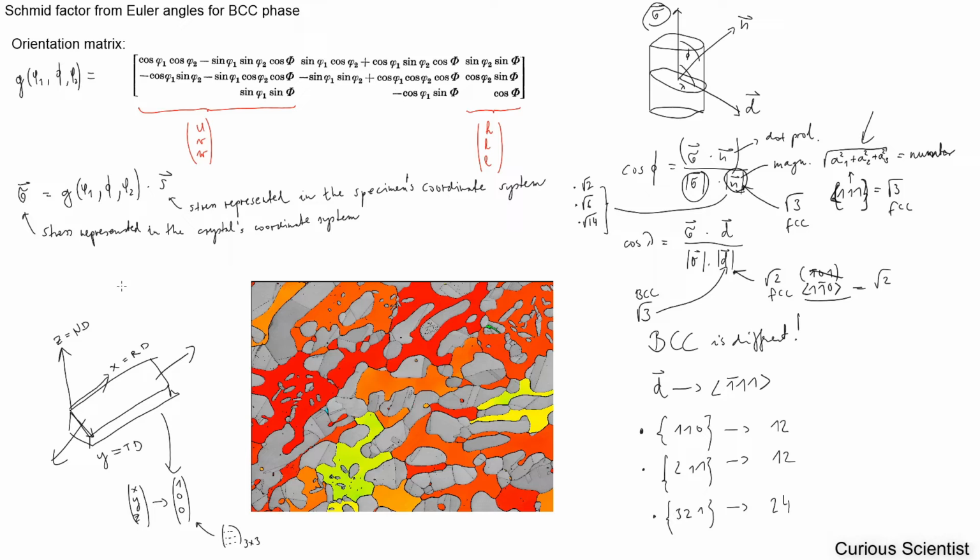So these Euler angles basically define that this much you should rotate in this direction, and that much you should rotate in that direction. And what you see here, this huge matrix, is basically the product of those 3 consecutive rotation matrices. So this is just a single matrix.